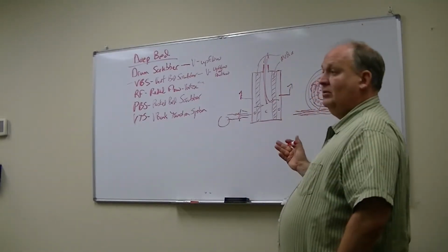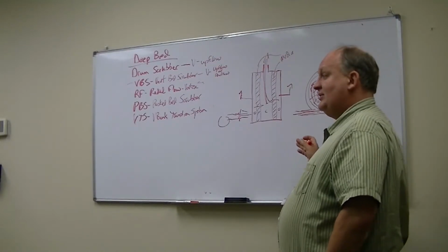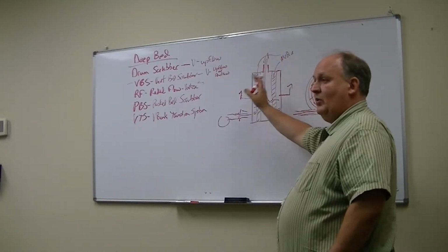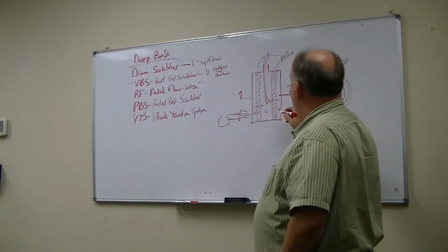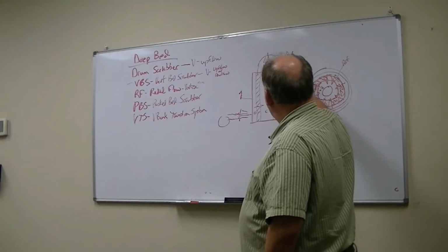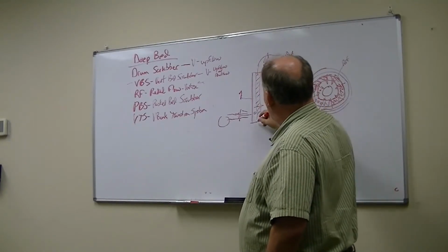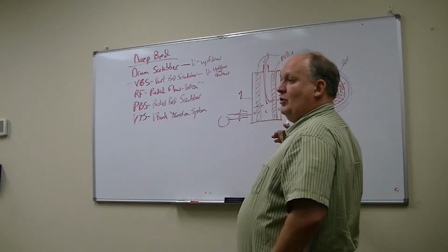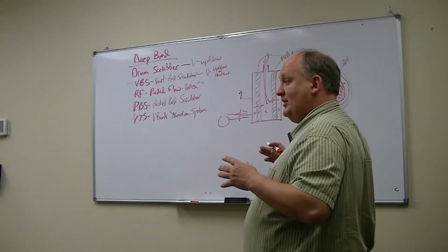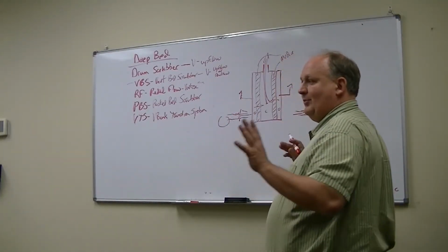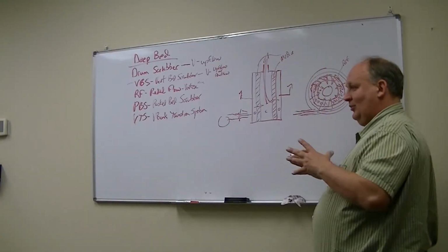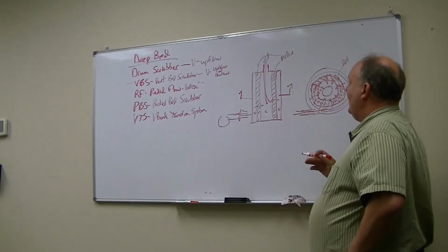So now, what sets the design of the velocity through the carbon? Well, now you have to determine the area of this whole cylinder here and your total airflow, and then you can figure out your velocity based on that. We can have a spreadsheet set up to be able to do that, because it gets a little more complicated because you're dealing with cylinders and everything here.